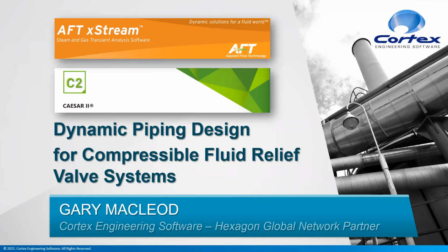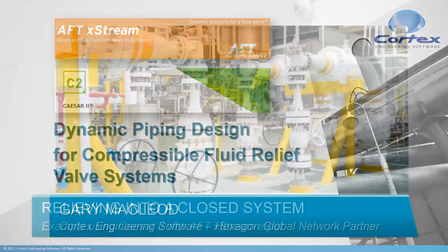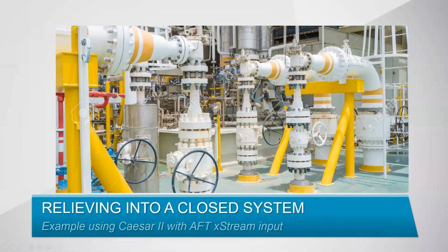IFT Extreme is new to the market. It's a program that will provide dynamic solutions for compressible fluids. So let's jump into it. We've got a lot to do. What I want to do is first look at relieving a relief valve into a closed system. The reason I've chosen a closed system rather than an open one or one venting to atmosphere is that it poses some interesting problems to the engineer.